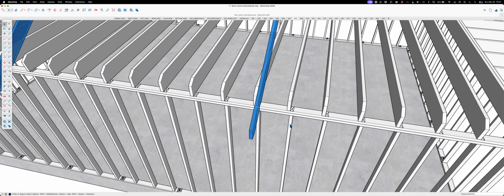And I'm not a big fan of 2-foot on center roofs. That's truss mentality. And people are like, well, the plywood's rated for it. Yeah. Have you ever looked at a roof that's 5 years old or so, and you're in snow land? You'll see little troughs happening between the trusses or whatever rafters they used. And that's partly because everybody goes to the minimum, because most people are dollar focused. They go with the cheapest because they've been misinformed to think that all houses are equal, and they're not. So build and then own it.